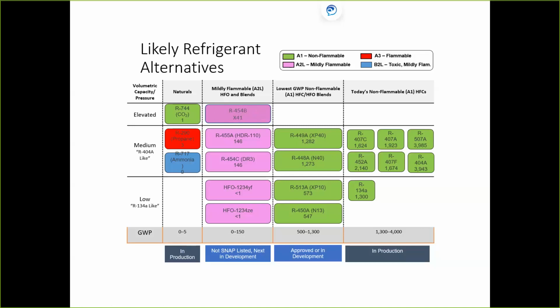Again, they announced it. Carrier also was the one that announced, if you remember, that new refrigerant years and years ago called Puron, that was R410A. They were the one that announced that years ago, and everyone soon followed. There have been some big companies like Trane, for example, that have decided they're going to go with 454B. I don't know all of them off the top of my head, but stay tuned with that. Be prepared for that. That is going into effect 2023, and that is your residential and light commercial.